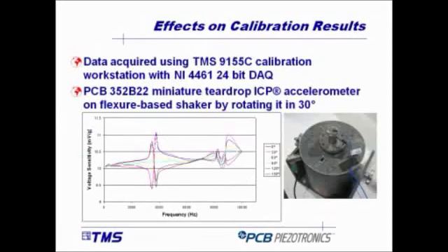So if I go to some test data that we've collected in the past that we obviously can't collect today, if we were to repeat this test over and over again, rotating the sensor in 30-degree increments, these are the variance and results that we'll get. And notice that sometimes we get stuff to pass in one area, but then fail in the other because the transverse motion is in different directions and depends on frequency.